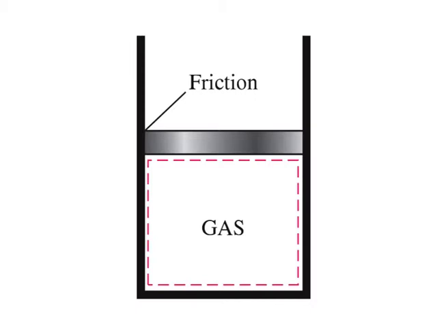When the direction of the motion is reversed, the bodies are restored to their original position, but the interface does not cool and heat is not converted back to work. Instead, more of the work is converted to heat while overcoming these friction forces that also oppose the reverse motion. Since the system, that is, the moving bodies, and the surroundings cannot be returned to their original states, this process is irreversible.